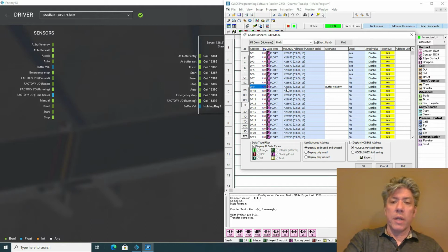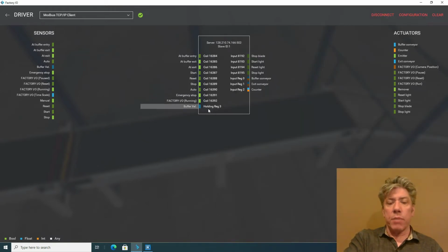And if I understand correctly, it actually is less of a Click thing and more of a Modbus thing. There's Modbus 0 based and Modbus that's basically 1 based. And so this is Modbus that is 1 based, which is actually preferred according to the things I've found. So anyway, 28689 would be 28688.